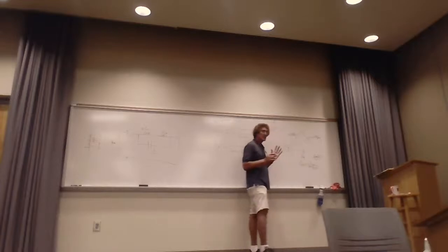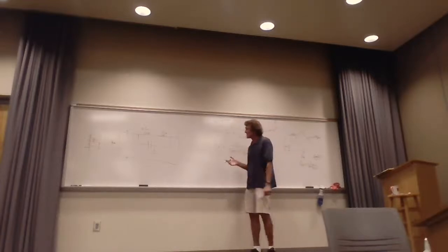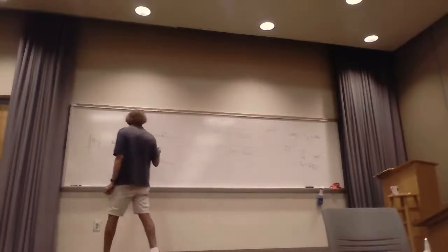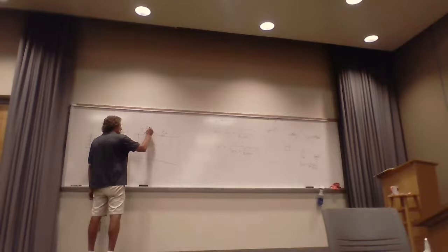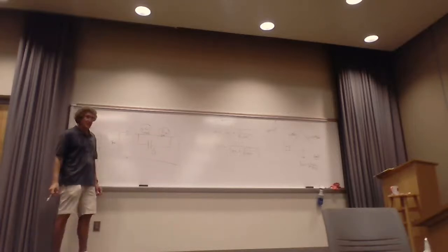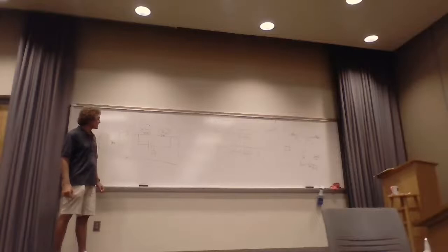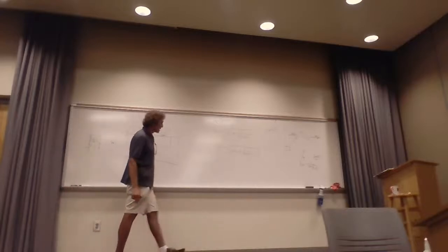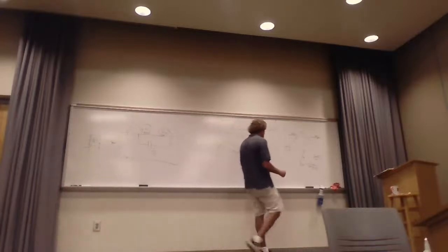And really, the way you find that out is you set this equal to this in magnitude, and you find that frequency. And you see that that's going to be 1 over 2 pi, and then it's R over L, if you take a look at that. But I don't worry about that frequency.